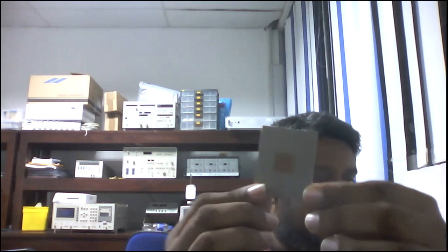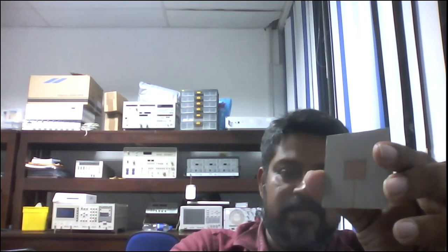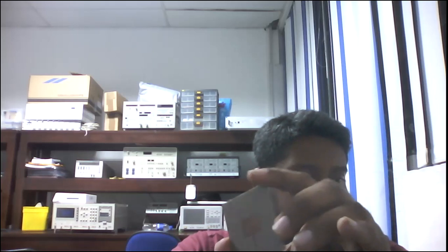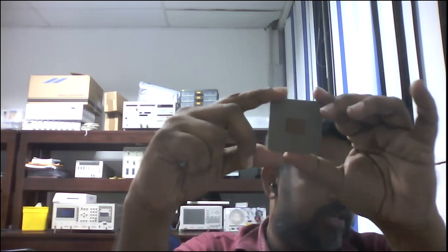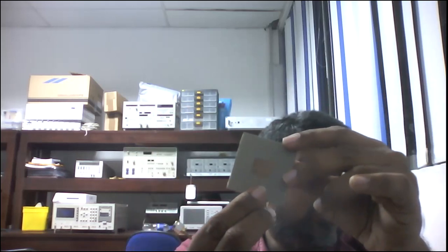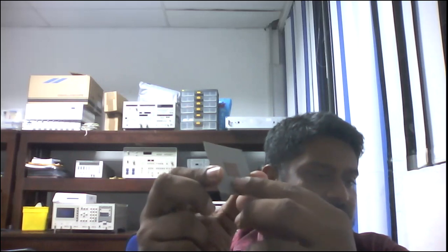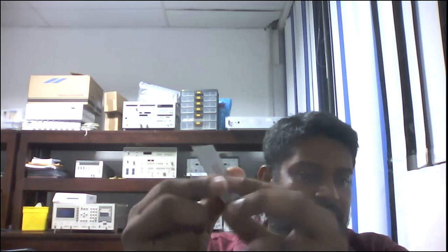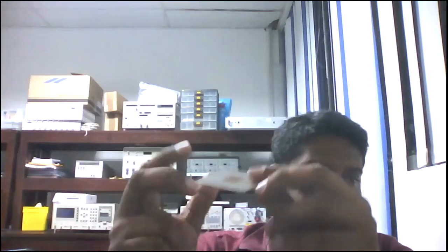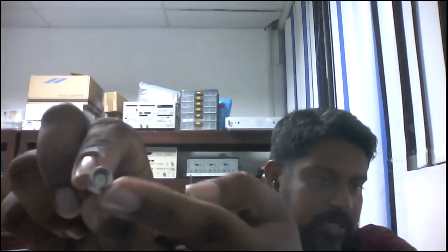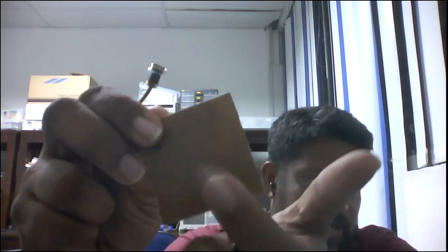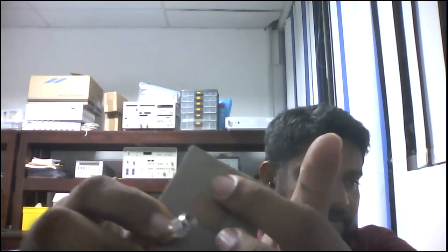Now if you want to connect an SMA connector, you can connect it very easily. There are SMA connectors that we can directly fix to this board. Next week I will show you. You can just solder that kind of connector here. This is the feed line, and you can connect the feed line to the inner pin of the connector. For the ground, you connect the outer part of the connector. The outer part is connected to the ground, and the inner part is connected to the feed line.